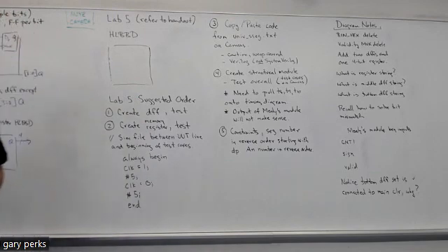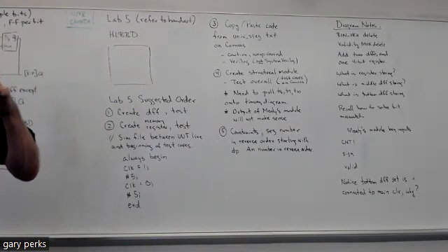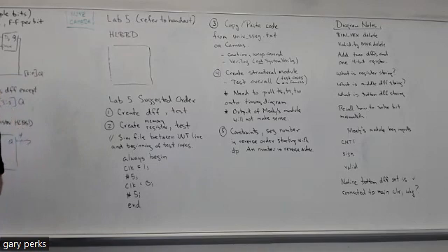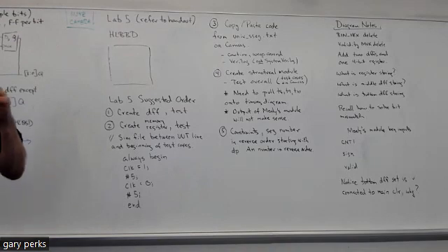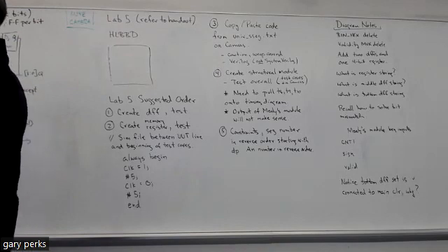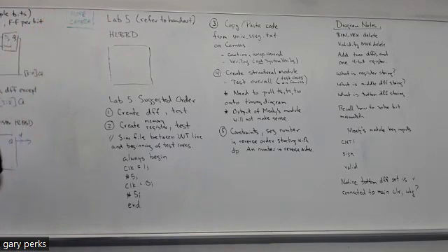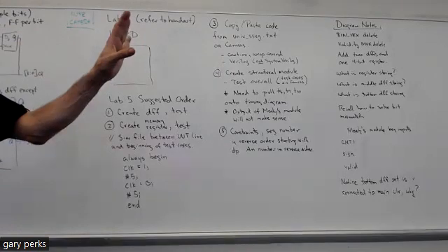Okay, and what time multiplexing allows us to do is to put data on all 4 7-segment displays at any given time. See, the way those 7-segment displays are connected, the way they're hardwired, is they're basically hardwired in parallel. So without a time multiplexer, the 7-segment displays are going to show the same number. For example, in your Lab 3 or Lab 4, where you have that mux that either passes through all ones to blank all the displays, or the 1110 that only lights up the furthest to the right display.